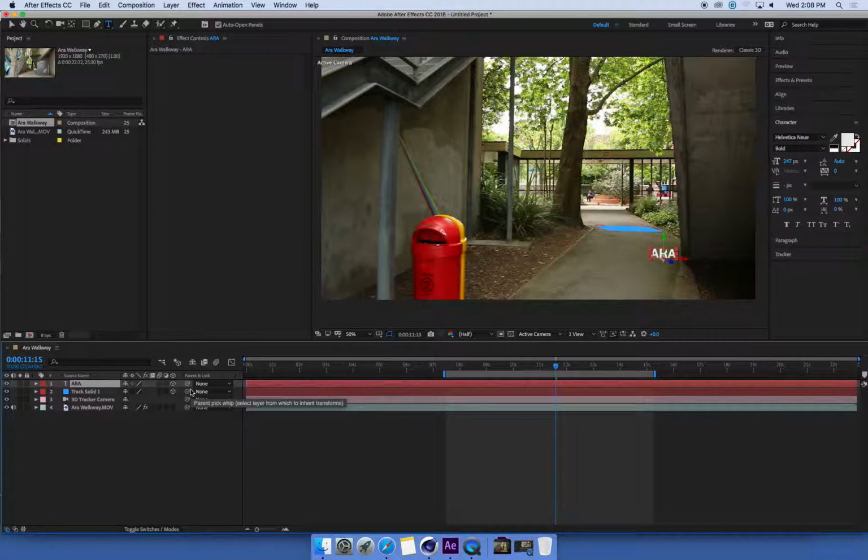So that makes any layer 3D, it puts it into 3D space. And by 3D, I don't mean that it gives it depth. I mean that that layer, which is 2D text, is now sitting in a 3D space. After Effects is what we call a 2.5D program. It has a three-dimensional world that you can arrange layers in, but they can only be flat two-dimensional layers. So we call that 2.5D. Hopefully that's not confusing.